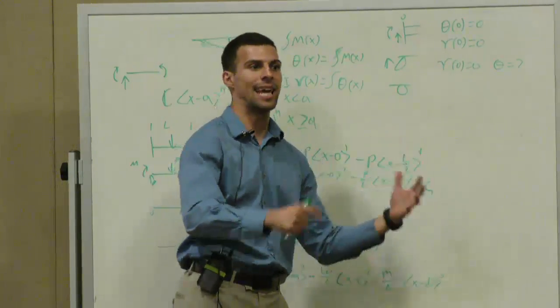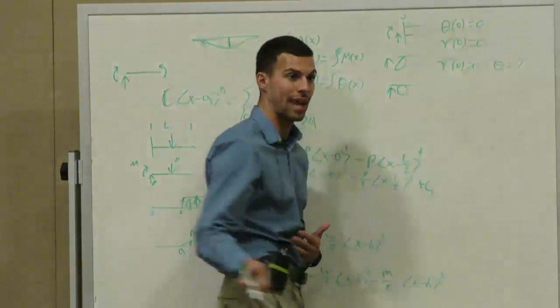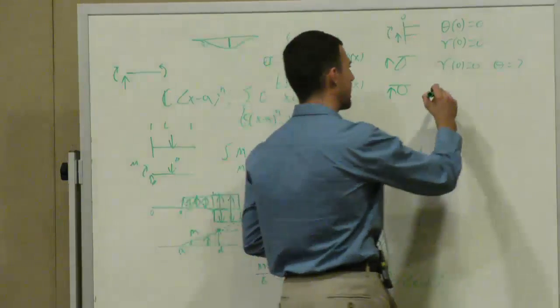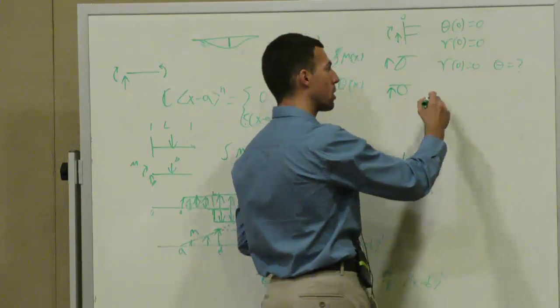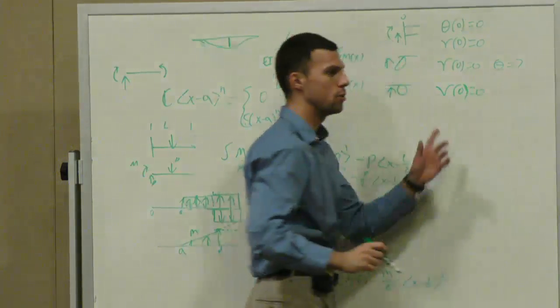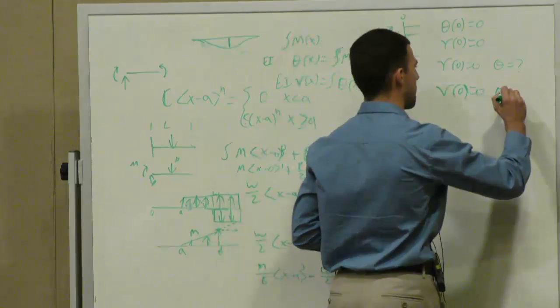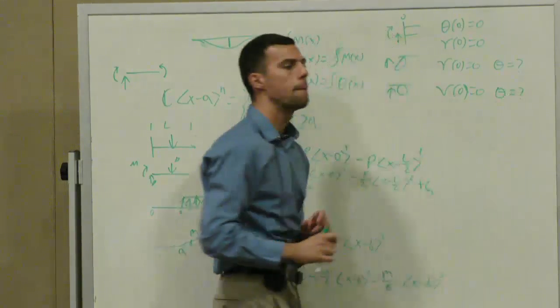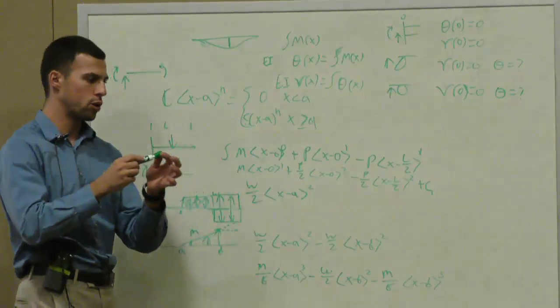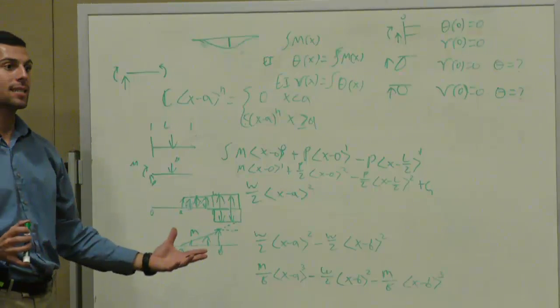But in academics, we usually say that roller connections have a vertical reaction. So at roller connections, you know that the deflection is 0. You still don't know anything about the slope, because you are allowed to bend around a roller connection. Does that make sense?